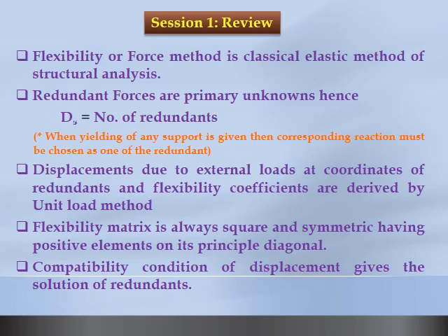But an important point I want to quote here is that whenever yielding of any support is mentioned in the problem, then the corresponding reaction must be chosen as one of our redundants. This is very important because any yielding of support will cause reactions at other places also. So we have to select that corresponding reaction as one of our redundants. We will see this in session 2 when we solve certain problems. The third point is